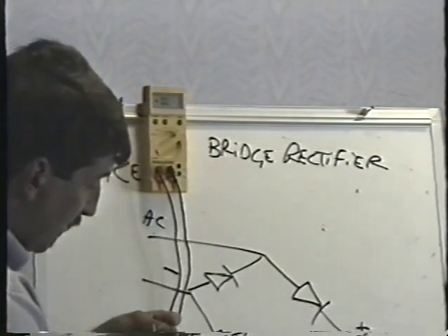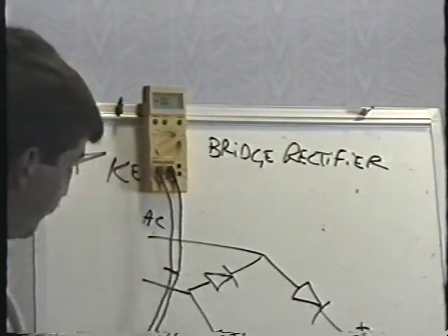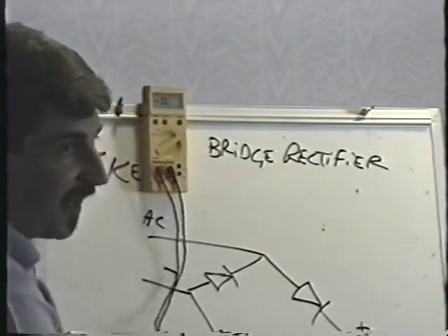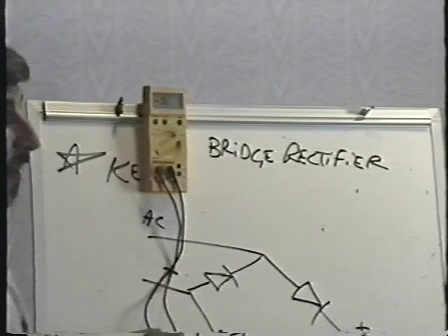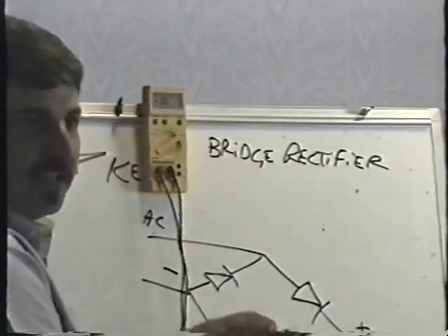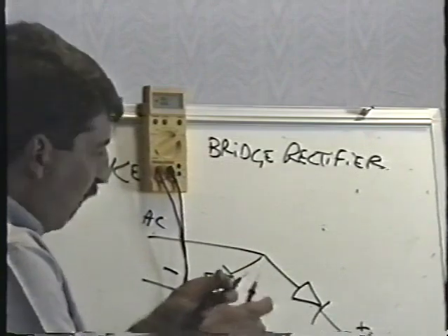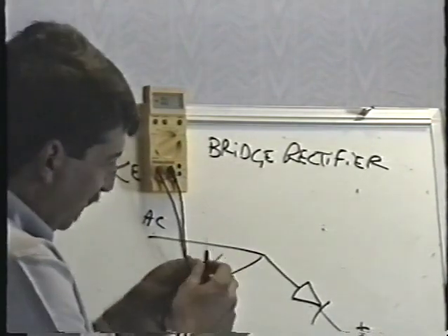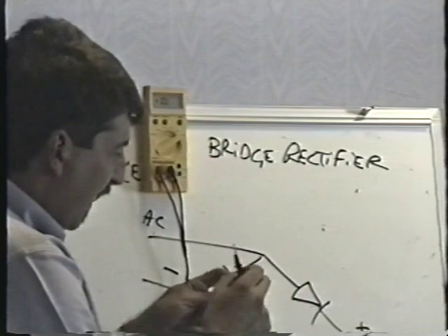Open the other direction. No, maybe I'm not. If that ever happens to you, by the way, touch your meter leads together and make sure everything is hunky-dunky. When you're working on something and nothing you're doing is giving you any voltage readings or any indication of anything, always touch your leads together to make sure that the leads are working and your meter's working. Okay, so let's try this again.